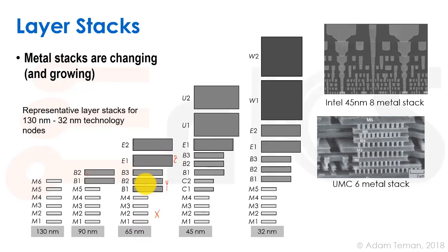So they're different thicknesses. And you see that the lower metal layers are for local interconnect, the median layers for maybe clocking or longer global routes, and the top layers for mainly power connections. And it gets more and more complex as we go, and there are more and more routing layers. And you see that the top layers are really huge, and they're just used for power routing, and the layers a bit lower than that for the main clocks and so forth.